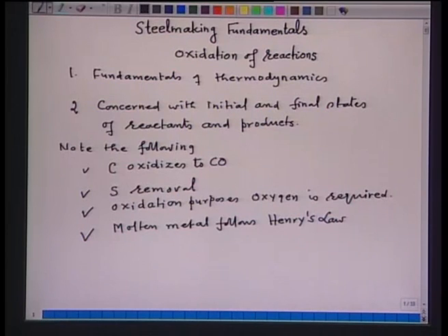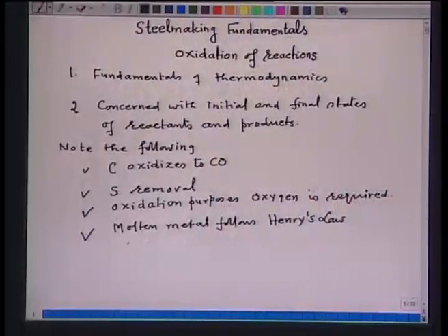Since molten metal is a dilute solution of impurity elements, we are very safe in assuming that the elements in the molten metal or steel follow Raoult's law, and we will also take 1 weight% as the standard state. We also assume 1 weight% standard state. Pure element is also a standard state.